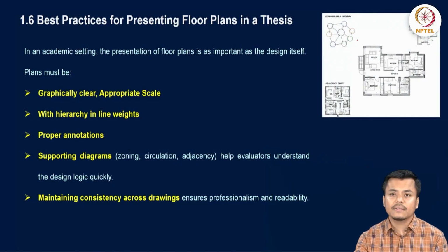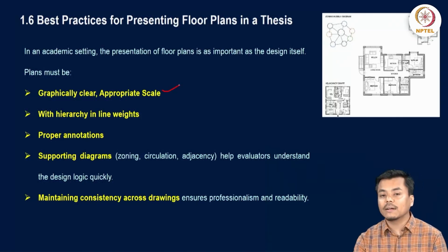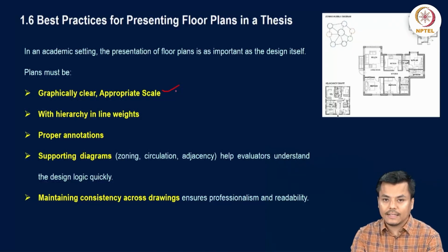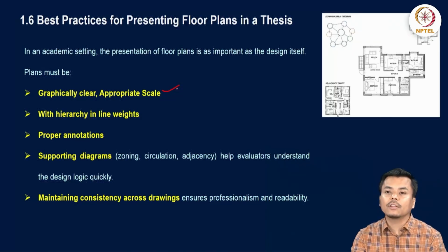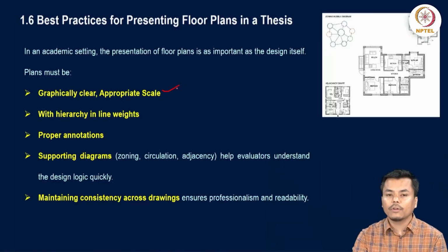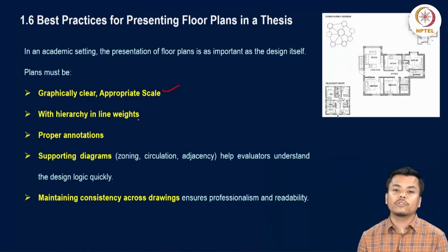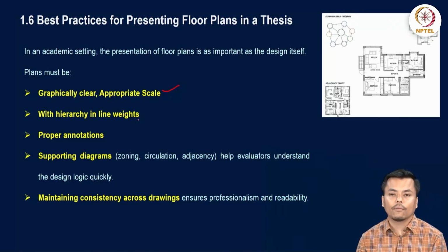The best practices for presenting floor plans in a thesis include that the plans must be graphically clear and an appropriate scale has to be used, so that one understands the volume of the space, and with full clarity we can see whether the space that you have thought of is appropriate to perform some kind of activity. Hierarchy in line weights is very essential so that we can differentiate between the different objects that are there within the floor plan.